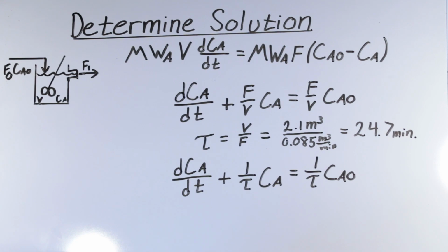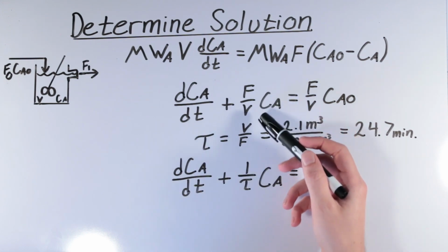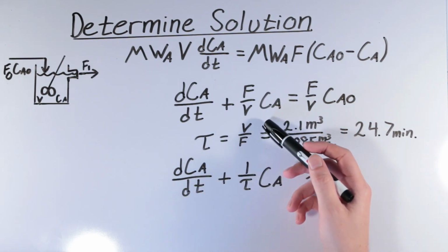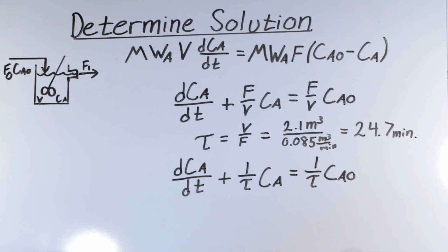Before proceeding to the integrating factor step, notice a property of this differential equation. Volumetric flow rate and volume are both constants with related units. Volume divided by flow rate gives a constant time, which is an important characteristic of the system. For instance, imagine how the concentration of component A in the tank would change in response to a step input change at different flow rates.